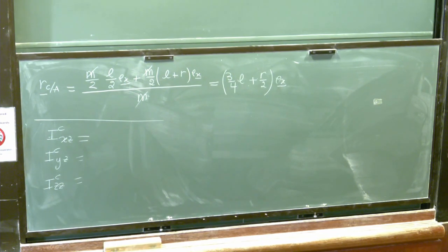Yes. Here we're going to show that the products of inertia are going to be 0. So on both sides, the EX, EY components are going to be 0. For example, for the example we did on Tuesday of the other bar, you needed the reaction moment. If you were to just cancel out the non-EZ components, you wouldn't get a reaction moment, so you would be doing something wrong, right? So I wouldn't just cancel because everything needs to be along EZ.